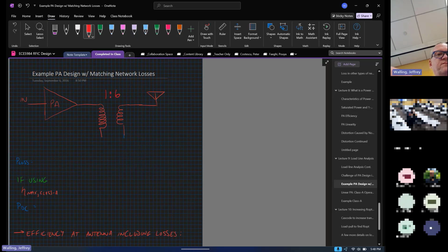All right, so let's assume that we've designed a really nice transformer, but even a really nice transformer in CMOS is likely to have something like 1 ohm of resistance just due to the metallization. So if we just have a piece of copper that's making our transformer, it's probably going to have 1 ohm. It's a pretty small amount of resistance.